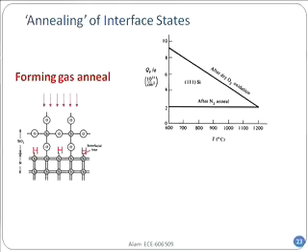And it's very important that you keep the anneal temperature very high, because if your anneal temperature is low, then the number of defects or dangling bonds that you have in the surface can be a very large number. One thing I want to point out is that this is the 111 surface. That's where the experimental data is reported from. But if it is on a 100 surface, it will be 1/3 less.